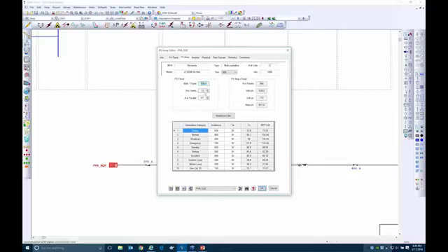And then I have about 12 panels in series, so that basically makes one single string of the PV system that we have. And that one string actually combines together in these panels to create essentially 440 volt DC.